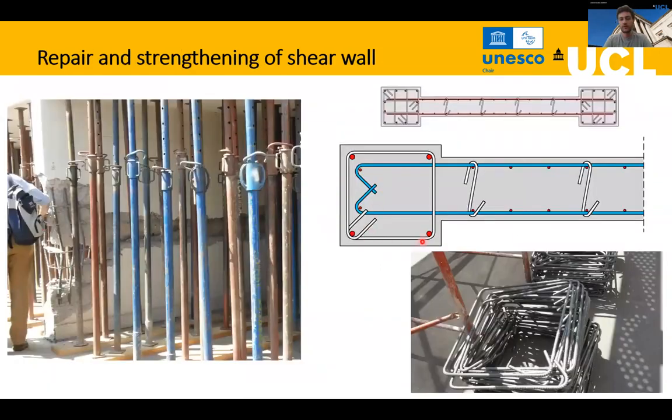So therefore, one of the best retrofittings, and even one philosophy of design of newly built buildings with this type of walls, is to add elements such as a column at the ends of the wall, so they can withstand the compressive and the tension strength when a lateral force comes, such as an earthquake.